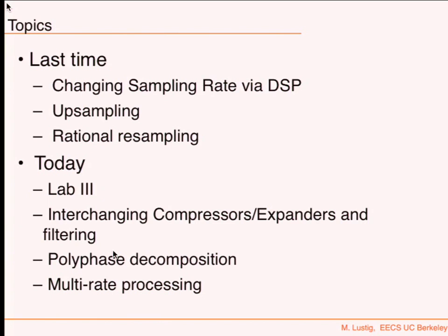That will lead to multi-rate signal processing, which we're going to talk about next time. And in multi-rate signal processing, if you think about it, it's kind of like a wavelet thing where we filter, downsample and then do the operation at a different rate and maybe go and upsample again and so on and so forth. So that's what's multi-rate. And you'll see that will really tie back to all the stuff that we learned about wavelets, and we see from a different point of view what that means and how they relate and how things can be reconstructed and computed very efficiently.